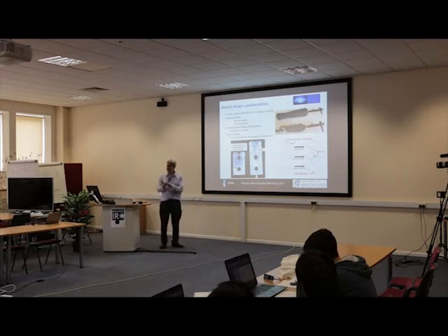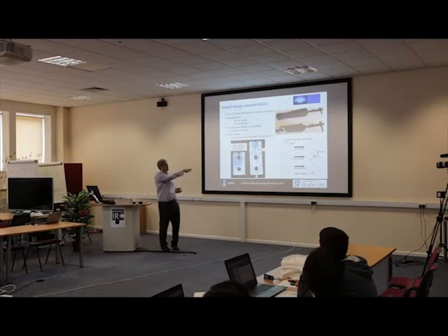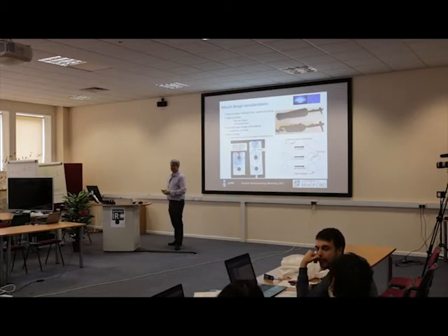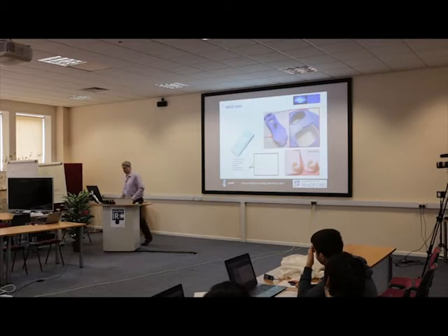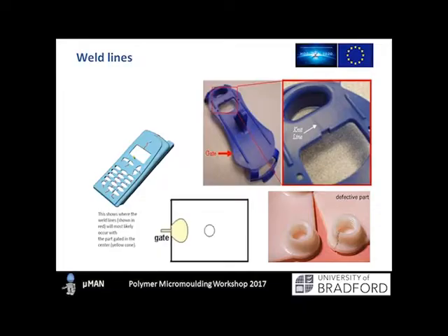And also the mechanical performance will never be as good because we're not getting the benefits of a nice shearing flow, which is causing orientation of your molecules and your alignment. We've got this much more random distribution with internal weaknesses as well. So these are things we have to consider. So as I say, on most components, you can see where these weld lines occur, and they'll exhibit themselves on the surface of the part, and they'll also cause stress concentrations as well. So if you don't control your weld lines adequately, you're creating local failure regions in your component.